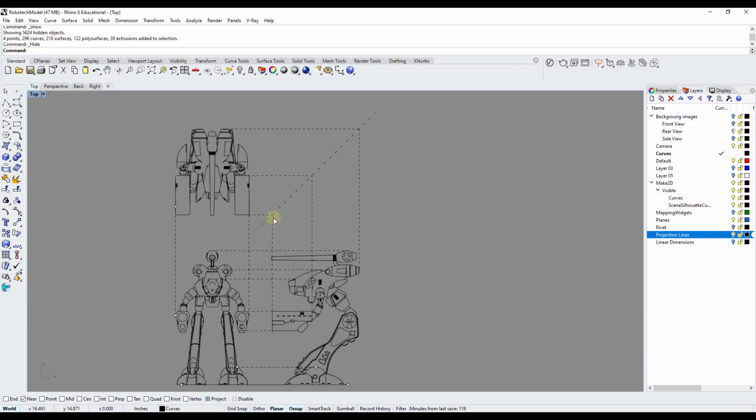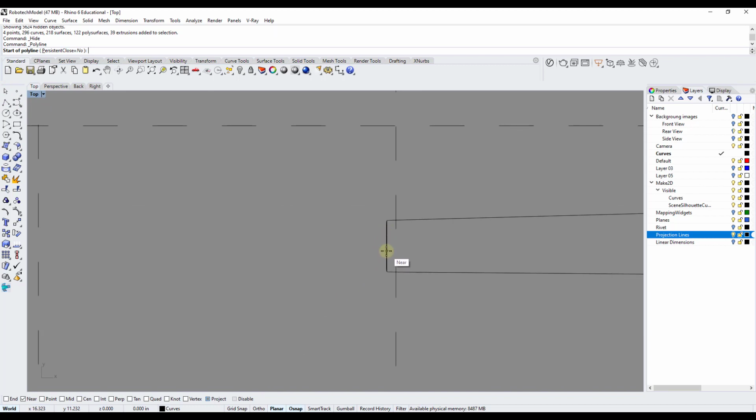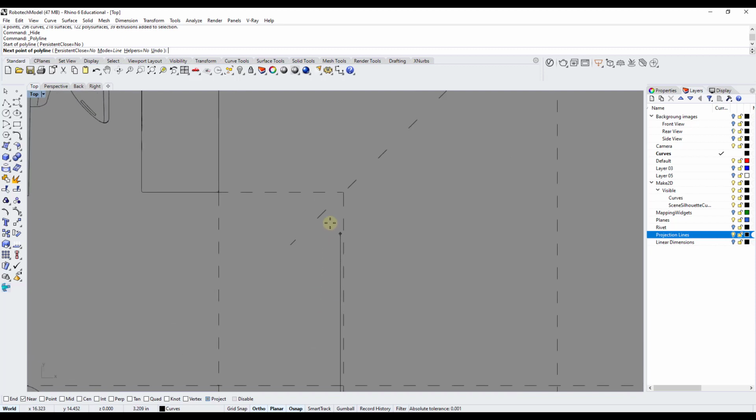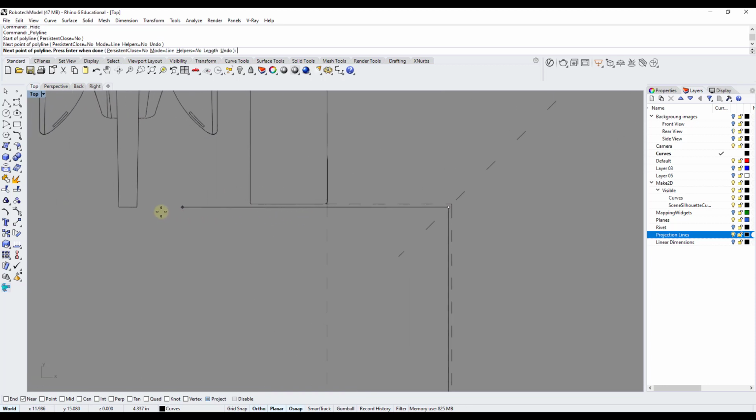Okay. So once I've created a line, let me demonstrate this for you. I use the line tool, and let's say I go to the tip of my gun here. I snap in here on my snapping toolbar, and I'm just going to press shift to lock it along the vertical line, and it's going to find the intersection of my angled line here, and I'm just going to bring it to the top view like so.